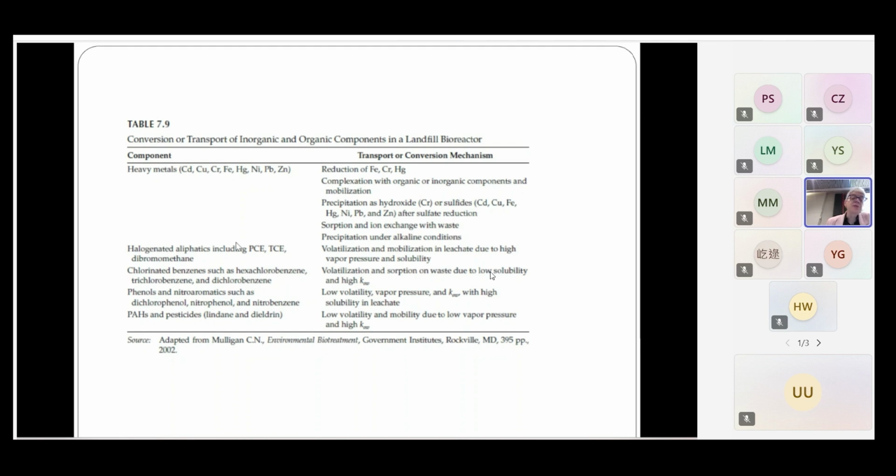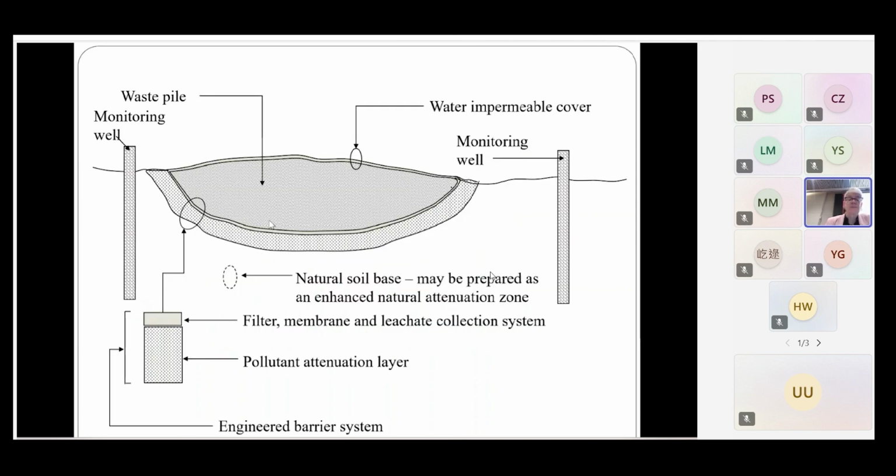You just have to make sure that you collect all the landfill leachate very well. You don't want to have too leaky a landfill, or else this is not going to work. So as I mentioned, this is kind of the normal landfill. You have your landfill, you have your membranes, hopefully underneath there, the geomembranes and so on, and then you'll have a clay layer underneath to be able to attenuate the pollutants underneath the landfill.